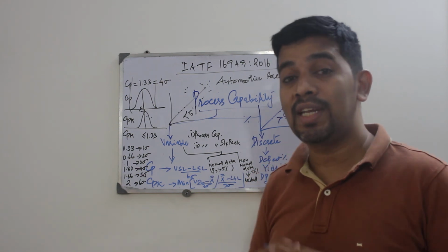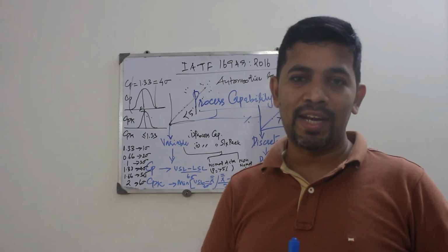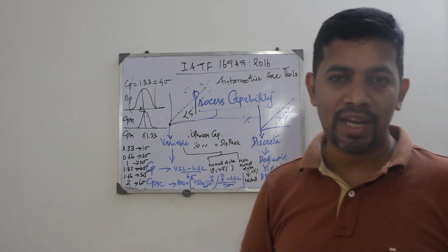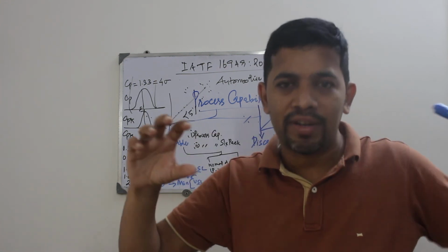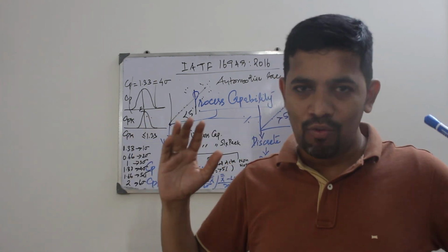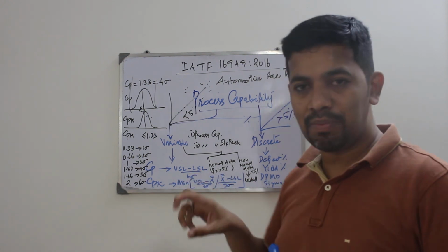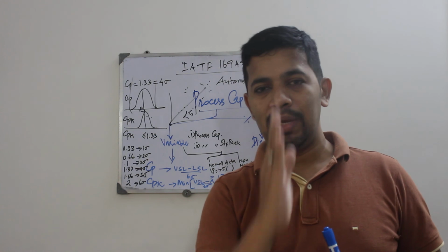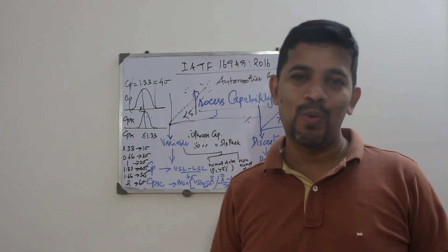And if you get less than 1, according to the TQM book, we need to take corrective action immediately and figure out the cause. Either you tighten up or loosen up the tolerance, or you work towards reducing the standard deviation. When the standard deviation is reduced, the CP or CPK value will go up, and when the CPK value goes up, your sigma value automatically goes up.